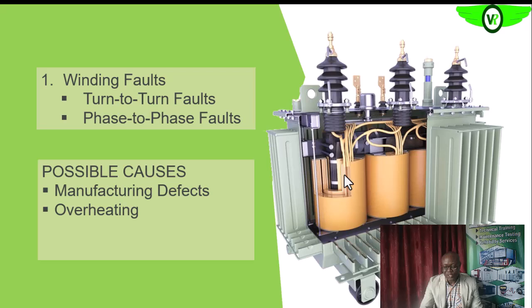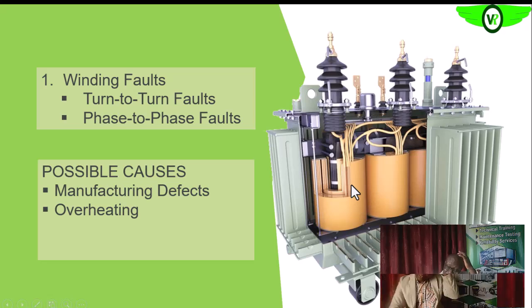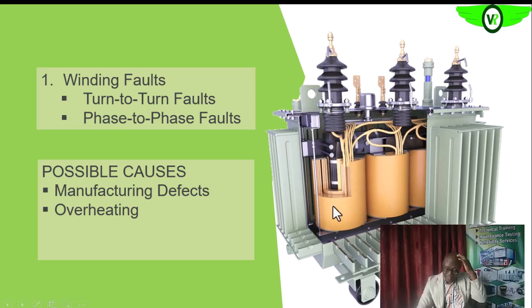Remember, during normal operations, it generates its own heat. Once overheating occurs, that means the heating will be more than what is normal, and that can cause deterioration of all of the components, all the materials within the transformer, the winding, the insulating materials, everything. Okay? And then result in eventual failure.